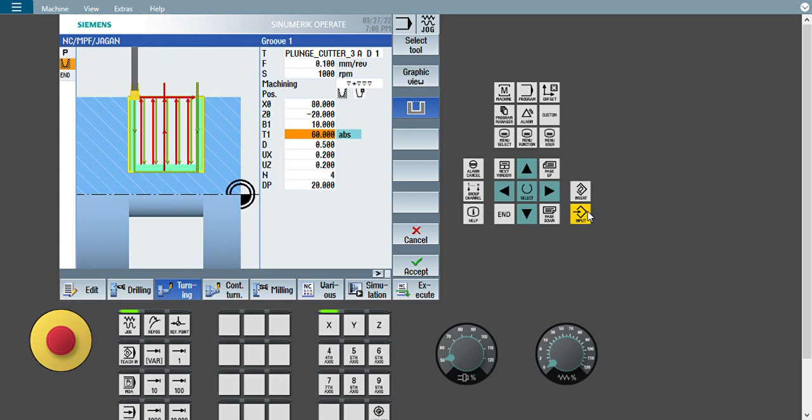Again I will say input, and there is D. D means depth of cut. How much depth of cut should I give? Here I will always think about our material condition, our tool conditions, our material properties. Everything should be considered here. Then and only then will your groove come perfectly. Otherwise, your groove will give a lot of chatter marks and vibrations. So we should be very careful to give the depth of cut.